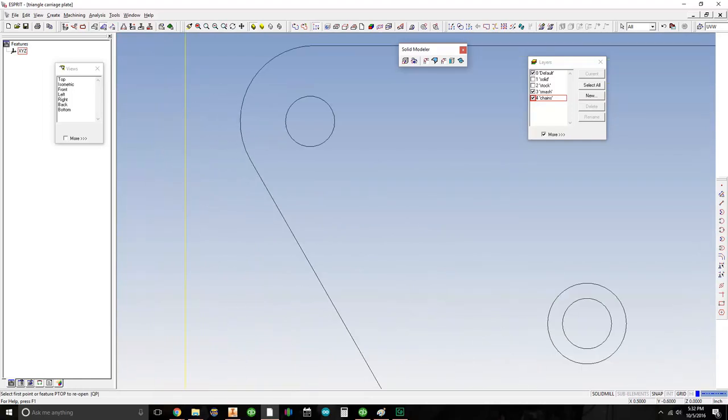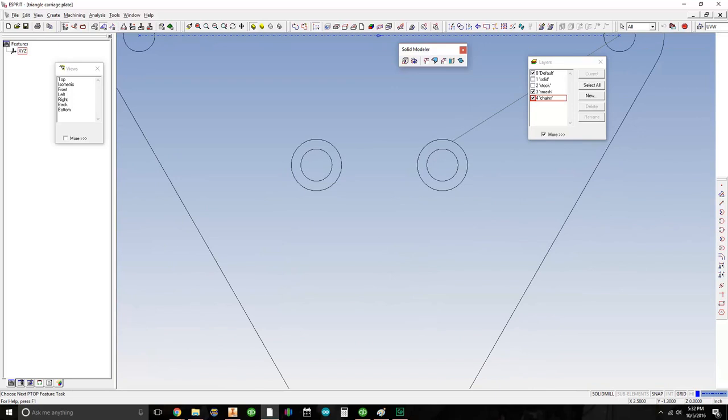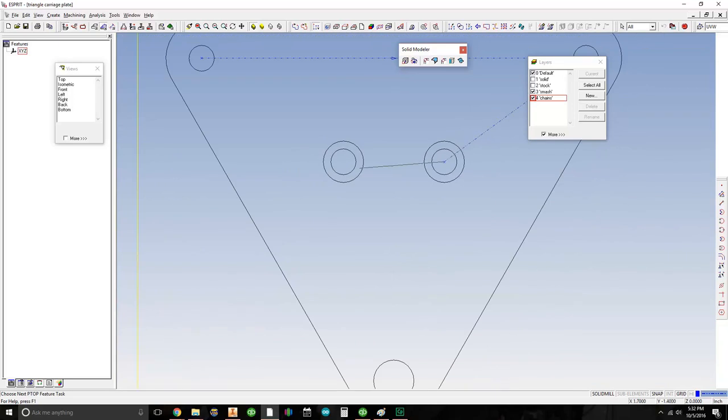Make sure when you hover over the arc that you get that center snap point. Sometimes you'll get close, but it's not there. See how it pops up right here and here. So I'll go ahead and go to stop. Now I have my point-to-point. This is a 5mm hole, so I'm gonna just type in 5mm holes.